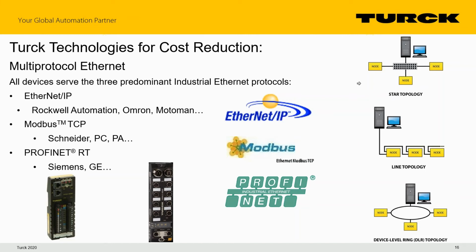So star topology is pretty much always supported because there is no need for a switch on the block. Line topology, we support with our switch. And again, every time we put a node in, we have this built-in Ethernet switch, we gain another 100-meter run to the next node. So that is what allows these systems to spread out over very long distances.